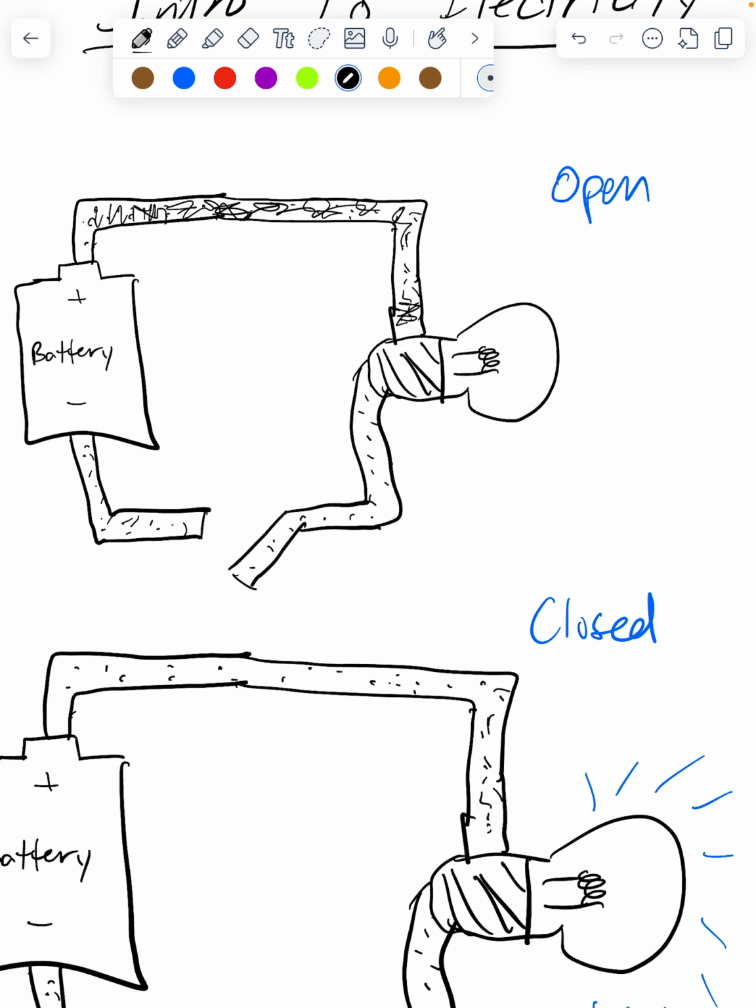The one key idea to get across, just to have a more accurate understanding of how this works, is that the wire is already loaded up with lots of free moving electrons. So the wire contains many free moving electrons. Now, they're not all moving in one direction, and that's why it's not called an electric current or a flow of electrons, and that's part of the reason why the light bulb isn't lighting up. The electrons are moving in random directions because right now there's no voltage being applied to the circuit because it's open. But the wire contains lots of electrons right at the start.